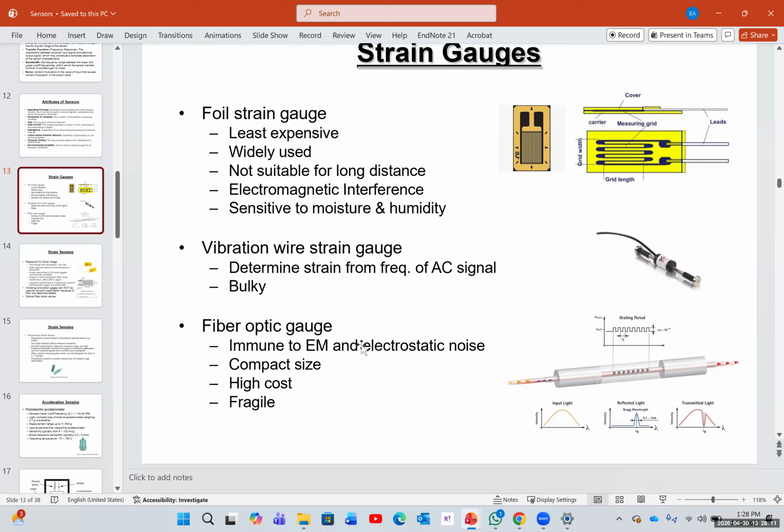FM, frequency modulation, is completely different. You have a solid amplitude, but the frequency is changing, okay? So this is, for example, 0, 0, this is 1, 0, this is 1, 1. So by changing the frequency, you convey the information. And then we have QM, QPM, QAM, different types, which are phase shifting. I don't want to go there, it's a completely different course. You have communication systems 1 and 2, which are analog and digital. But for now, know that this signal frequency determines the size of your antenna.